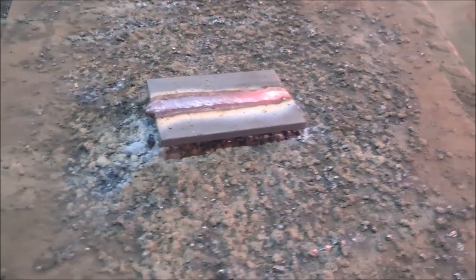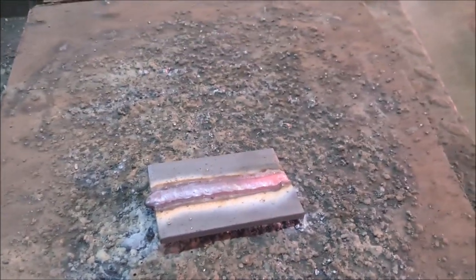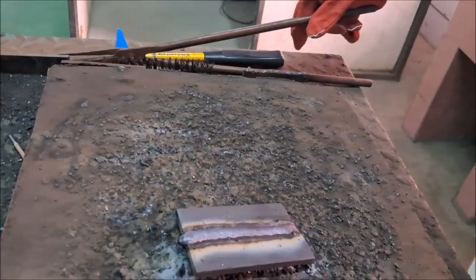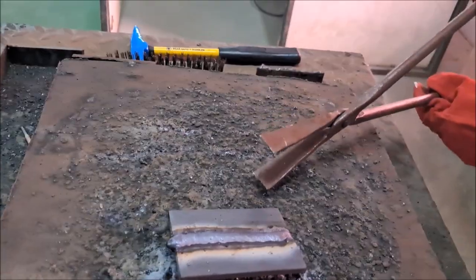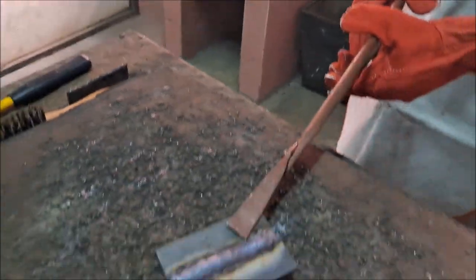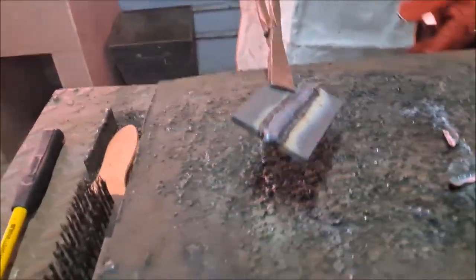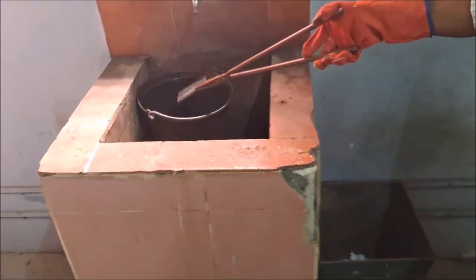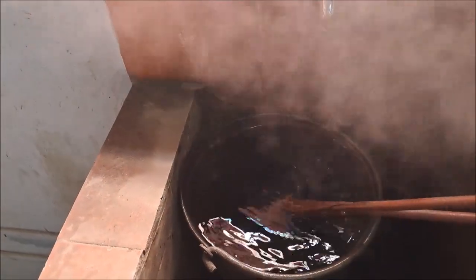That is alright. After completing, hold the holder in the stand. Thereafter, take the tongs, hold the workpiece, and dip it in water. See that? Hold the workpiece carefully and carry it out. See the welding, both sides are fully penetrated. After that, go and dip it in the water. After it reduces,